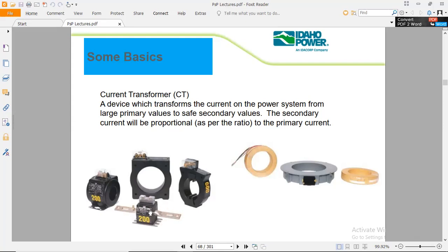which sense current in a single phase particularly, but these are the kind of current transformer which measure the current all over the three phases directly. Three bus bars of phases red, yellow, blue are going through inside the CT, and current would be sensed.